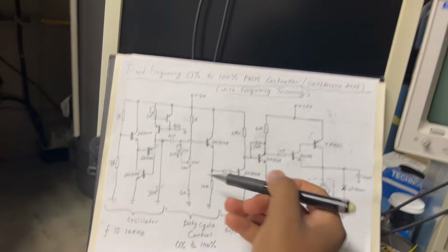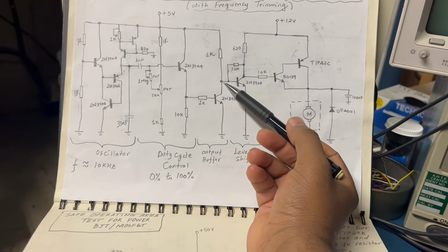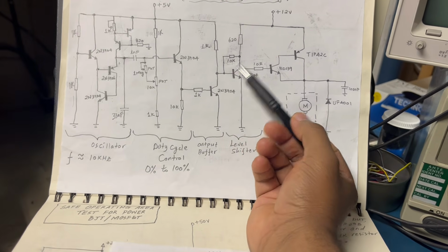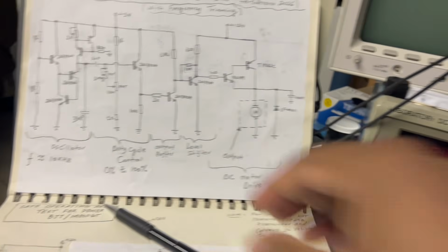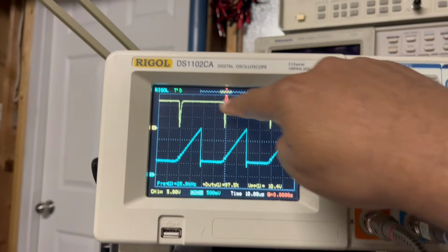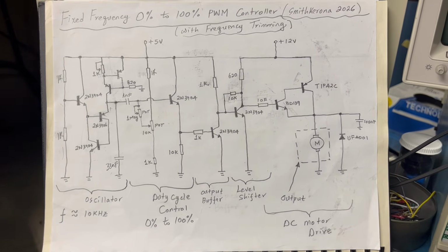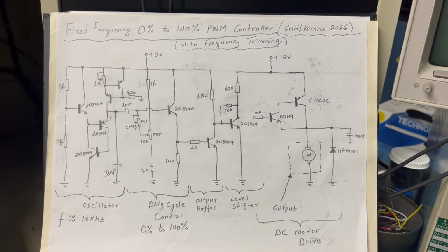Okay, so now basically this transistor is turning on and off. If we look at the collector side of this transistor, we'll basically see the 12 volts that comes through here. It will look like a nice square wave that's turning on and off, right? And that's what this upper waveform is. So I just wanted to make a quick video trying to close out how this circuit works and describe it fully.